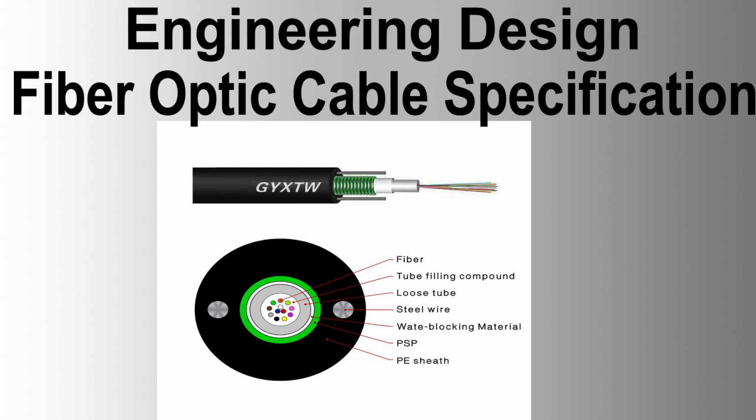Outer sheath. Composition. The sheath shall consist of a tough, weather-resistant, high-density polyethylene HDPE, hydrocarbon-resistant PVC. Quality. It shall be circular, free from pinholes, joints, mended places, and other defects. Jacket thickness measurement and eccentricity standards apply. Optical fiber identification. Color coding. Each fiber in a tube must be distinguishable from other fibers in the same tube by means of color coding ink discernible throughout the design life of the cable as per EIA TIA 598A.